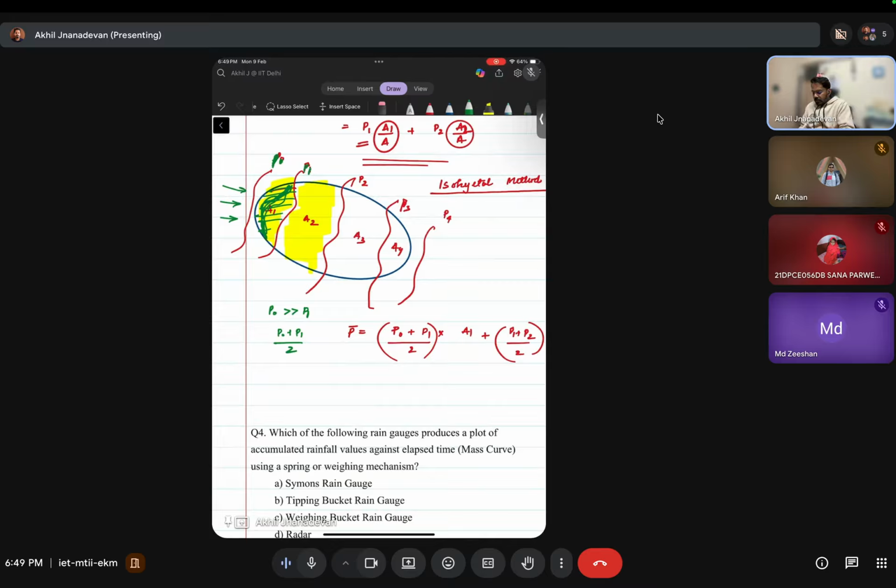So earlier what happened is we were placing rain gauges within this particular line. Anyway, P1 is in a rain shadow region, so we will automatically get smaller values, and we are taking the average and reporting that as the Ganga Basin's rainfall. That is something wrong, right? So here, if we make a contour map with the isohyets, the entire extent will be covered. It has the rain shadow region within it, and the high rainfall region also within it. So indirectly, the orographic effect will be taken into account.